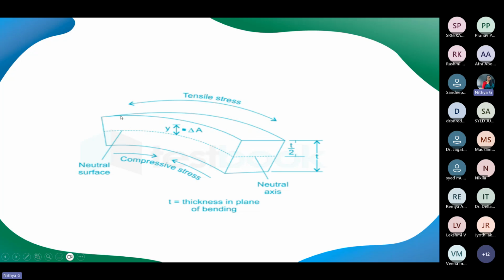Okay. So what did we understand? Cantilever beam, one end is fixed, other end is free to move. So there is a stress created across the body. Outer surface will have tensile stress, whereas the inward surface will have compressive stress. But the region which is exactly in the middle of both the upper and lower regions of the cantilever beam will be stress free.